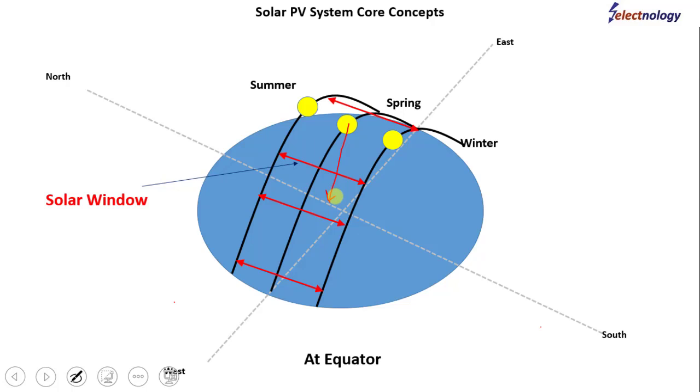There could be another way, that is, if we have some moving mechanism underneath the solar PV module so that it can produce maximum power throughout the season, so that the solar PV module moves its face towards the sun when the sun is changing its position to receive maximum sunlight to produce more power. In that case, it is a mechanism called a tracking system. The tracking system is installed with the solar PV module. Obviously, it is a bit more investment and more expensive.